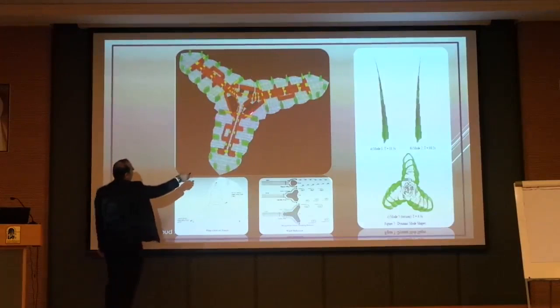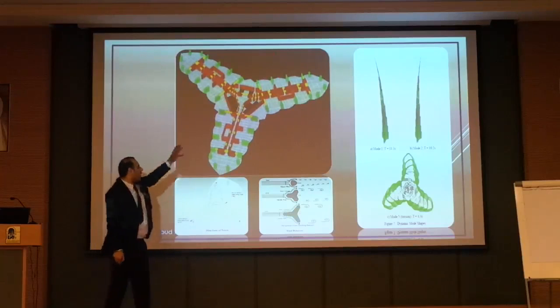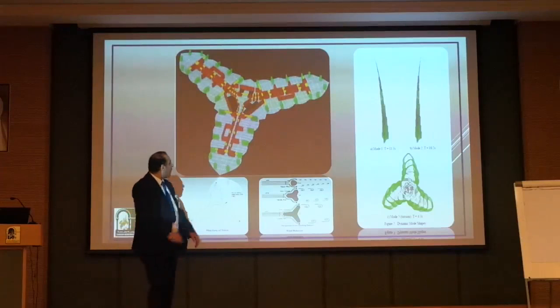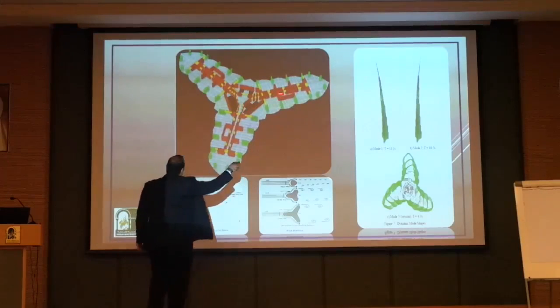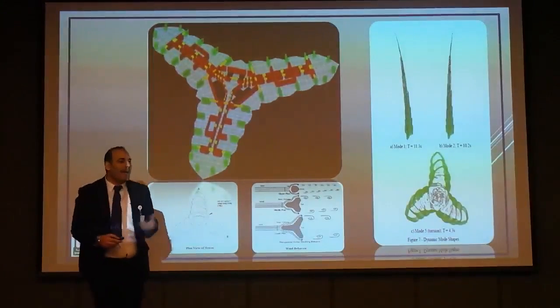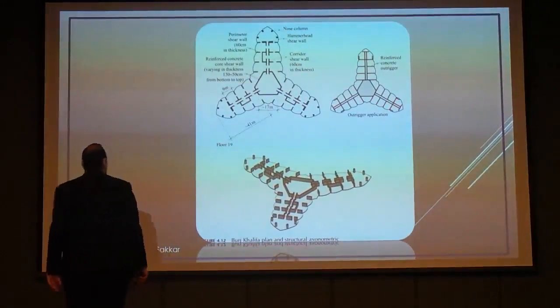Make a hexagon shape. It's a hexagon, but not with equal sides. Hexagon shape to resist torsion. Make a shear wall everywhere to resist the torsion, even for each flange, and connect them by what? By a spandrel beam. Don't think that when I say internal core it's going to be continuous. No, we have spandrel beams. We say that a spandrel beam can make a coupled core, correct? Okay. So that is Burj Khalifa once again.